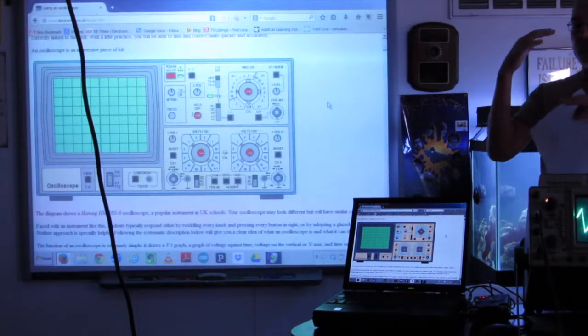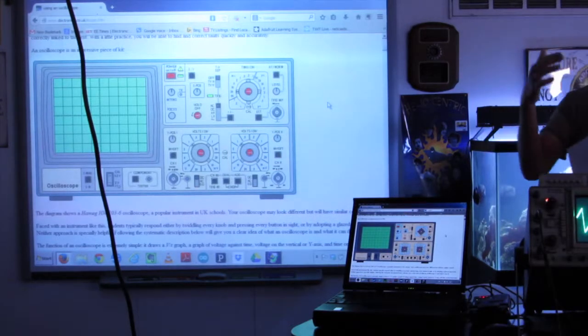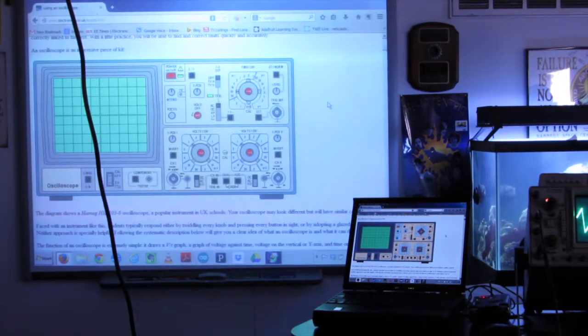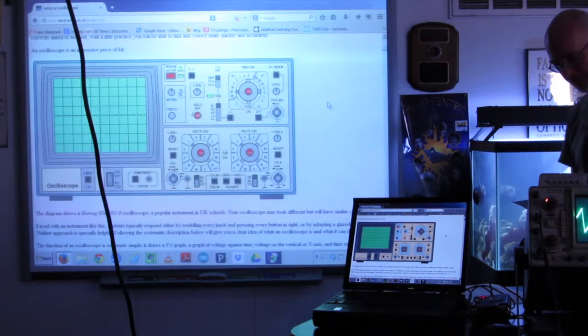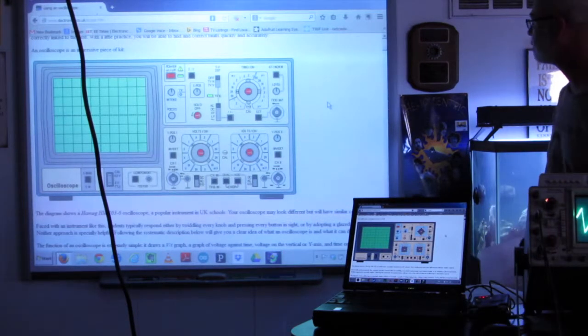So that means you can get 400 volts peak to peak on most typical scopes, and of course there's ways to expand that with additional attenuators, but you can probe your AC outlet and see your AC waveform easy enough just by going up on the ranges there.